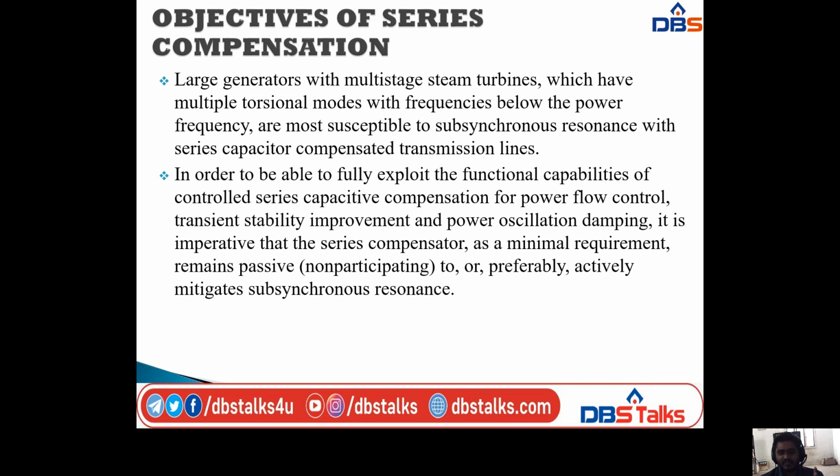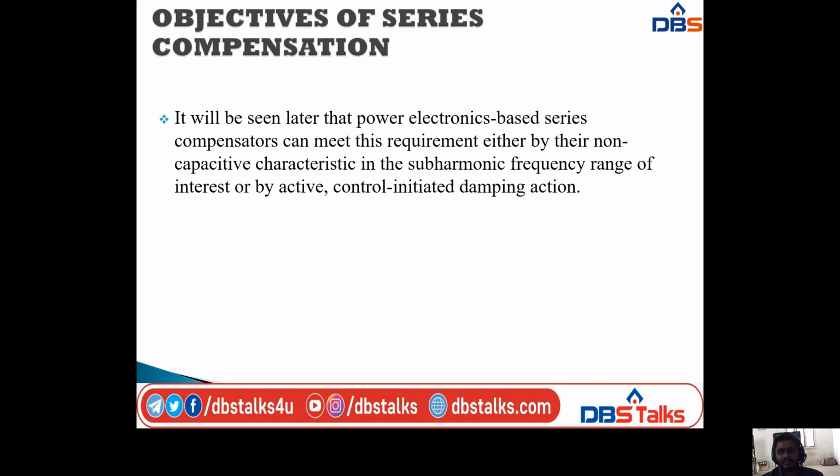It will be seen later that power electronics based series compensators can meet this requirement either by their non-capacitive characteristics in the subharmonic frequency range of interest or by active control initiated damping action.